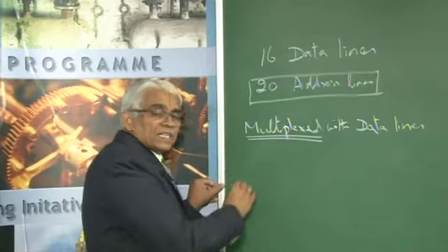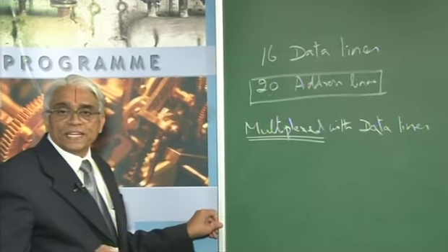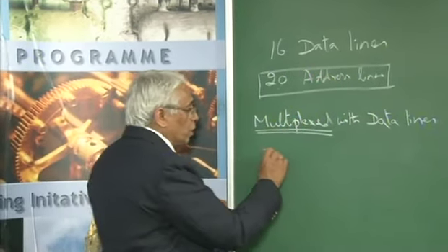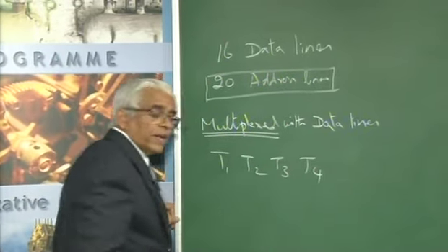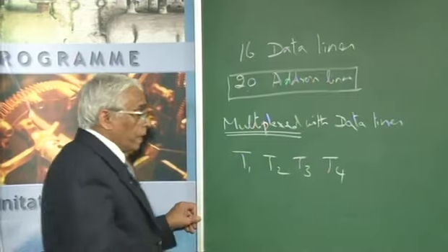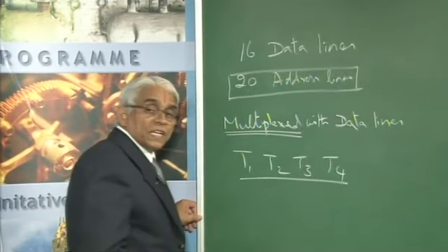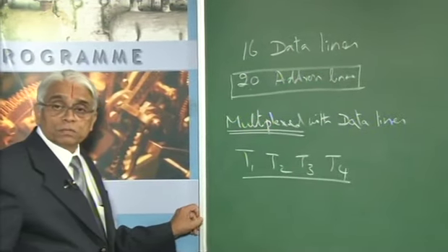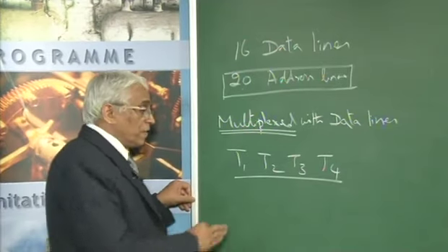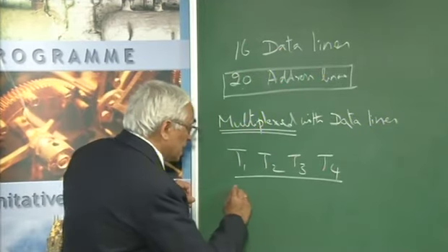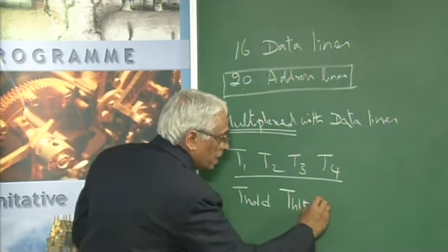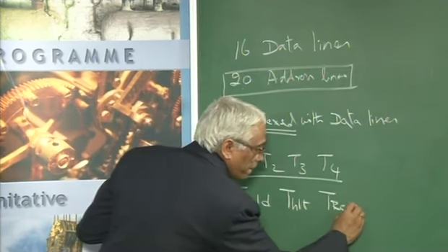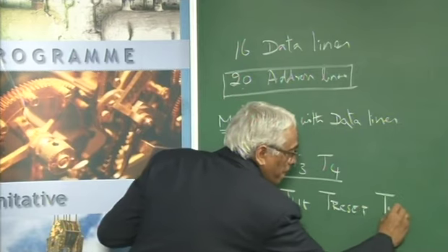The complete operation of the 8086 microprocessor is divided into states called T1, T2, T3 and T4 states. Each of these is 1 clock period in duration. The other states in which the microprocessor works are T hold, T halt, T reset and T wait.